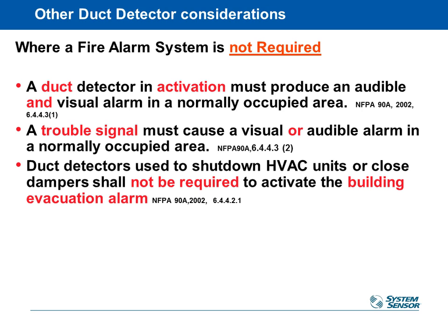And that detector must then provide both an audible sound alarm and a visual alarm in the occupied space. So not only does he have to shut down the fan systems in the air handling equipment, but he also has to alert the occupants in the space. So if smoke is detected, they'll be notified so they can then leave the building.